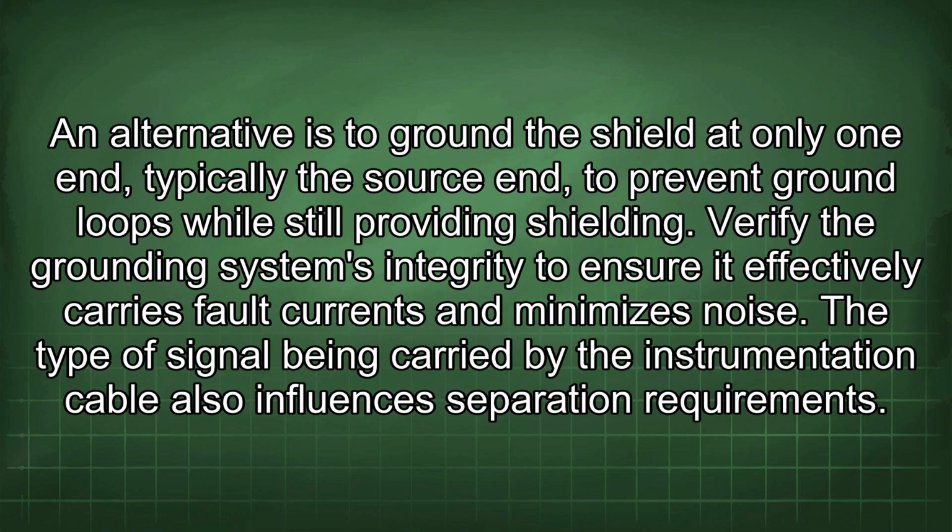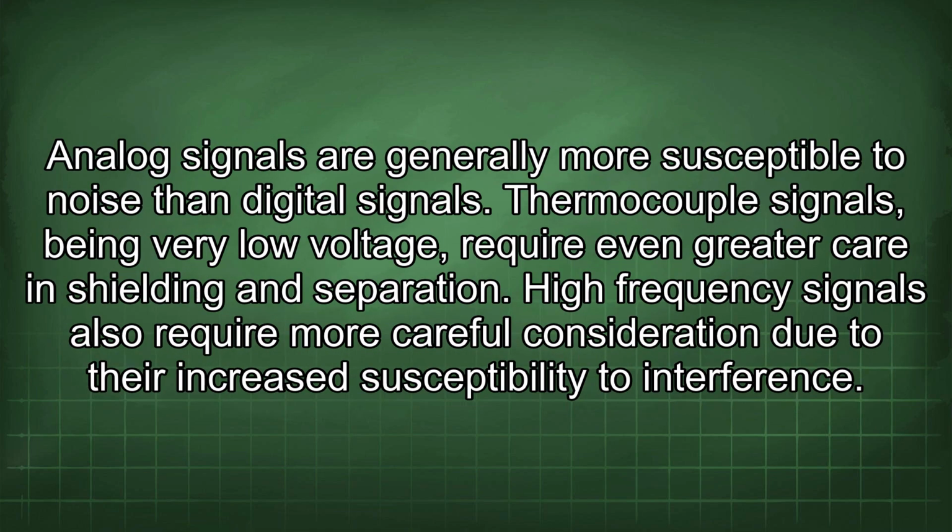The type of signal being carried by the instrumentation cable also influences separation requirements. Analog signals are generally more susceptible to noise than digital signals. Thermocouple signals, being very low voltage, require even greater care in shielding and separation. High-frequency signals also require more careful consideration due to their increased susceptibility to interference.